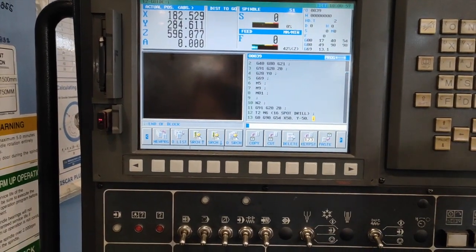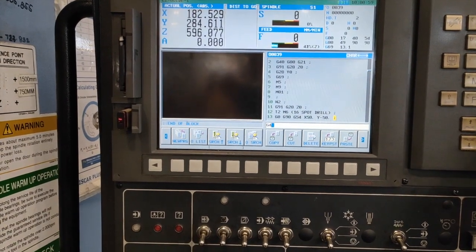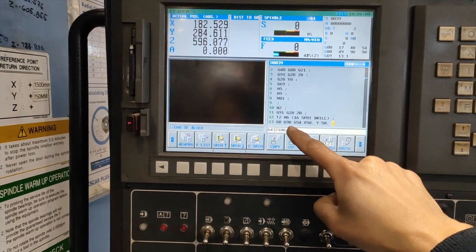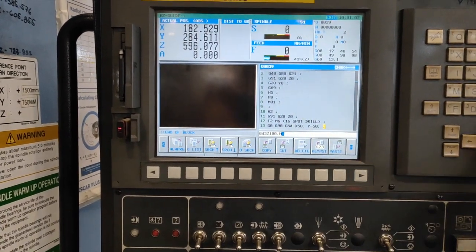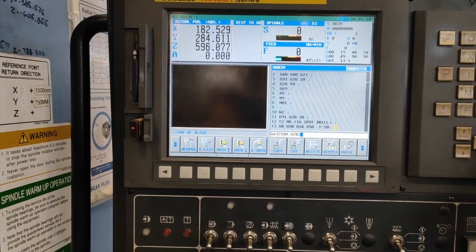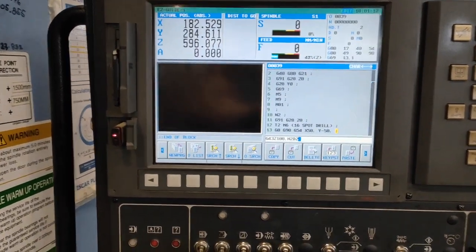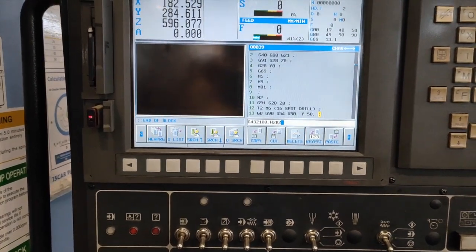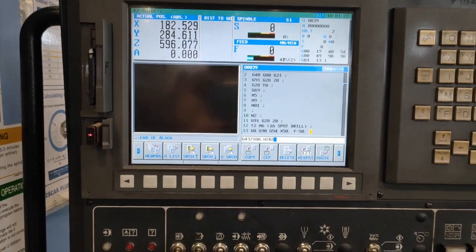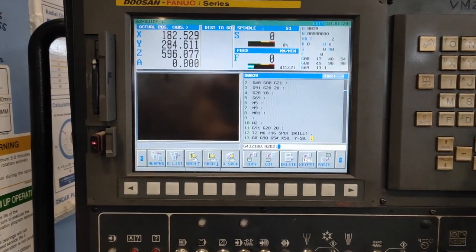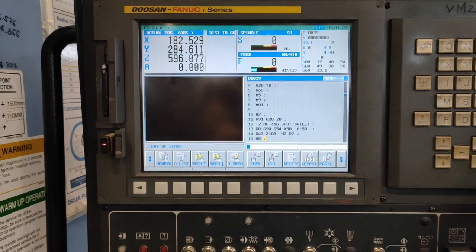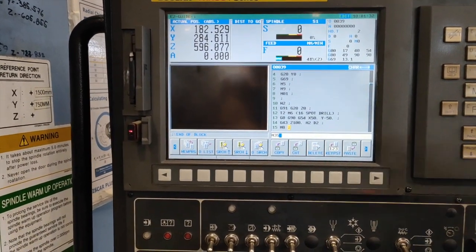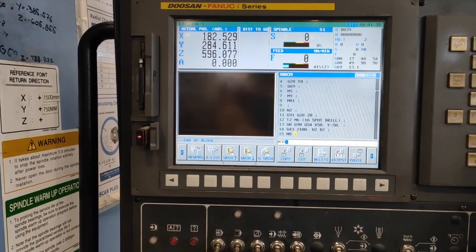And the next command I will do is G43 Z100, then H2, because it is tool number 2, H2. Then here I always put the diameter offset, the D, because I want to see it in graphics. It will determine how you set the diameter of your tool. And M8, and then the next command is M3 S. Let's say our spindle speed is 1000,